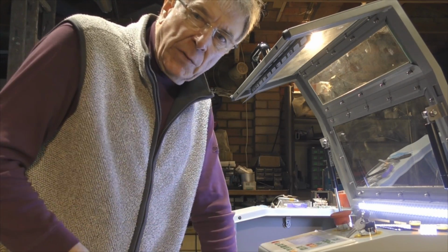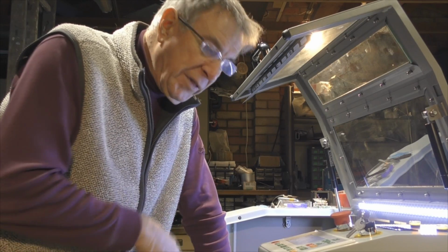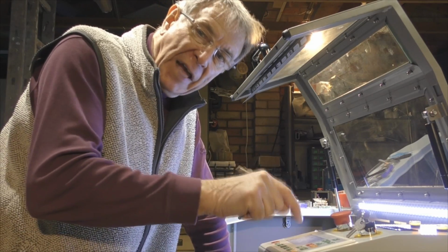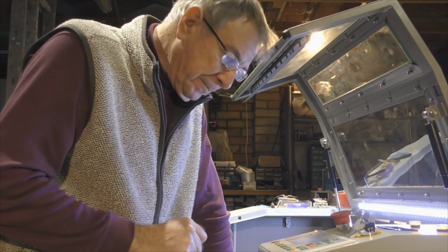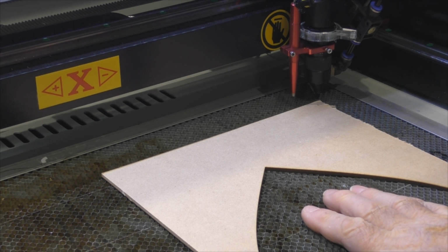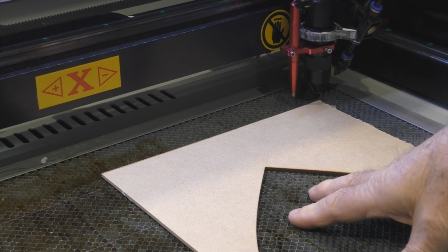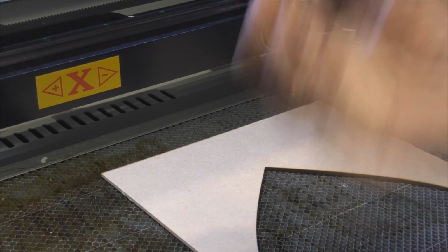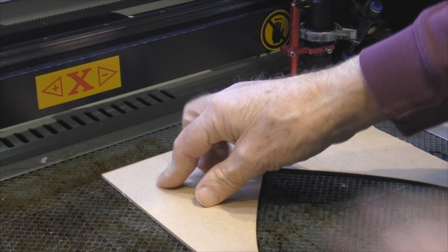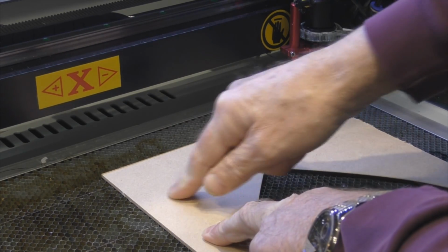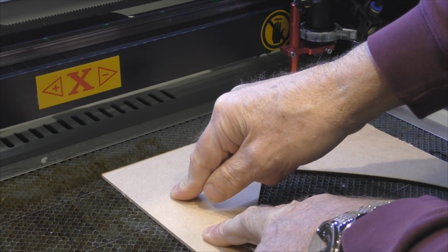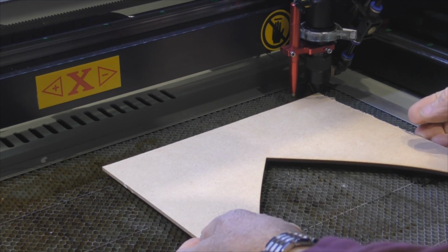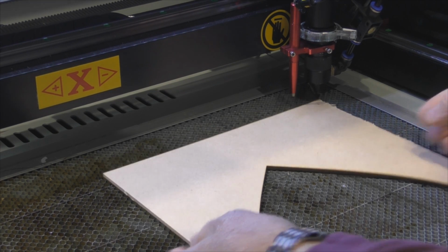So you can draw that in RDWorks and program it up with cutting parameters. It doesn't matter what the parameters are that you put in, because we're going to edit those here on the machine itself. Now, to do this cutting, we could use this table. The problem is, people think that you get good extraction through this table, but look, how much extraction am I going to get through here? The answer is very little. The way to get good extraction is actually to let it happen underneath the job like that.